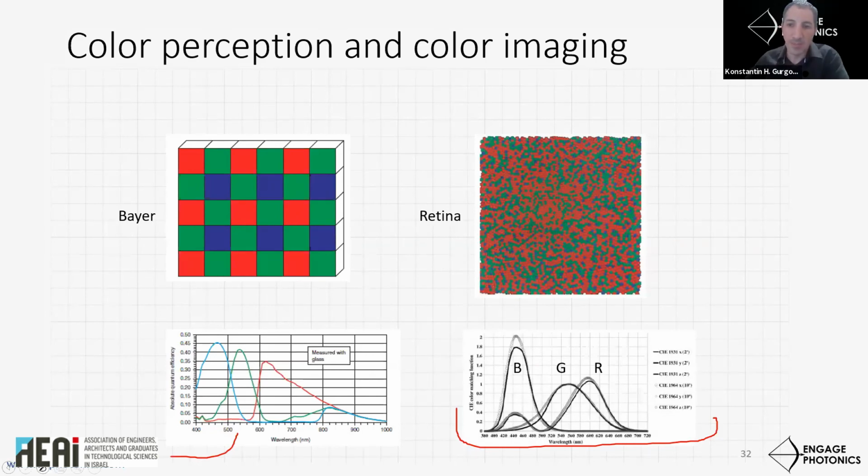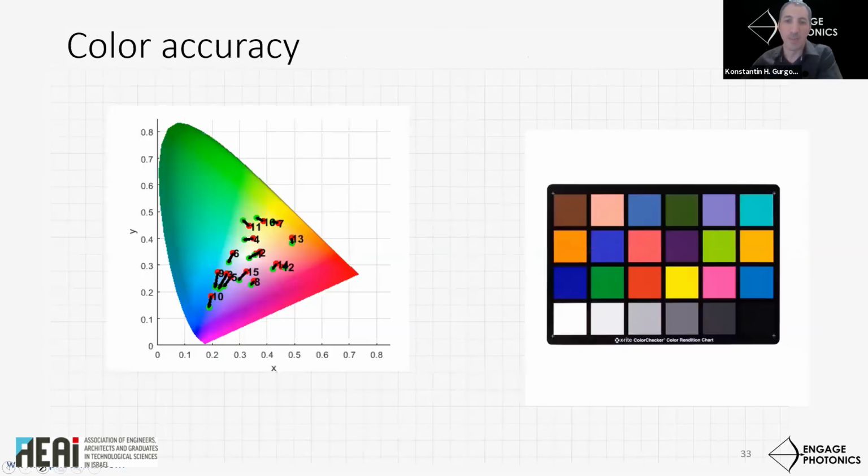Once the image is acquired, the DSP interpolates each of the 3 sets of pixels into 3 images, same size as the original matrix. And so the RGB image is actually 3 images. Obviously, sampling each image at half the resolution reduces the effective MTF of the system considerably.